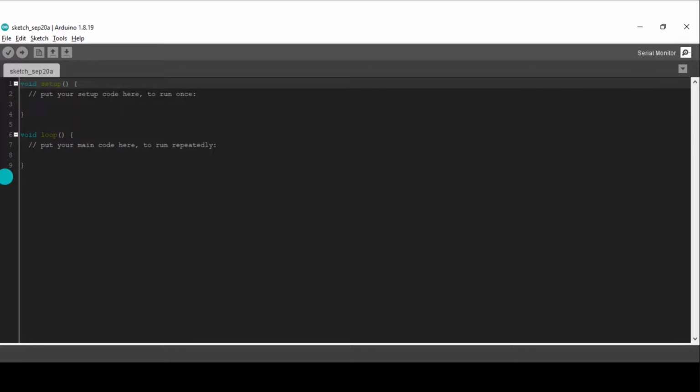Now we are going to run through an example of this serial communication before we begin the project proper. For the example, we will use the begin function for serial communication with the computer through the USB plug of the Arduino and set the speed of transferring data, which is the baud rate, at 9600. Then we will use the simple print function to print the text. The text we will be printing is "Welcome to this project" in the serial monitor. For this purpose, we will use the following code.